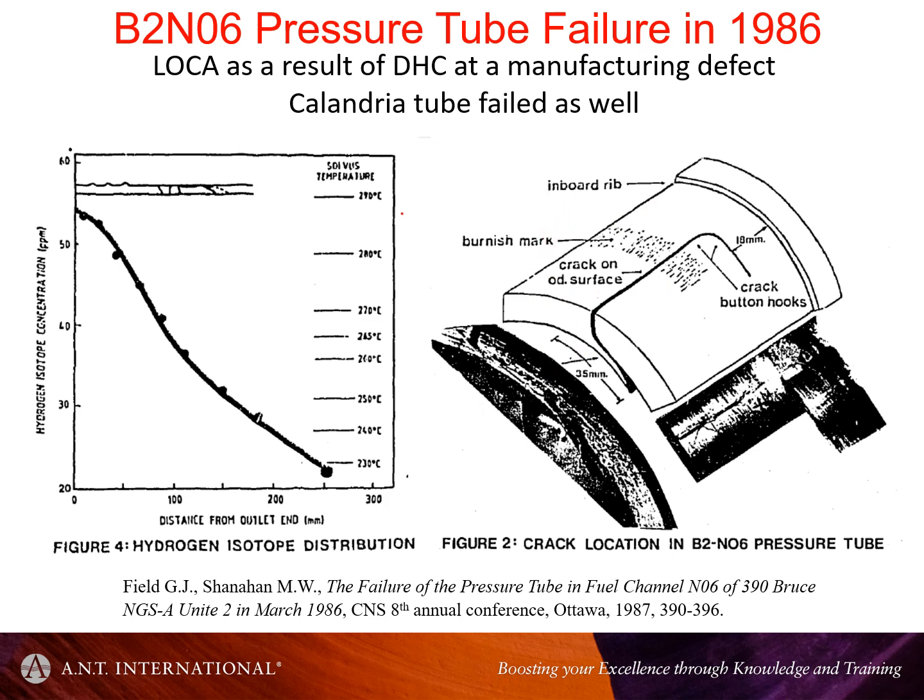But in that particular case, the weld in the tube, which was thinner than we were looking at, like 1.8 compared to 1.4 millimeters thick, was thinner, and therefore it let go under the system pressure. And so we had a catastrophic LOCA with a release of the coolant, primary coolant, into the calandria vessel, which contains the moderator.